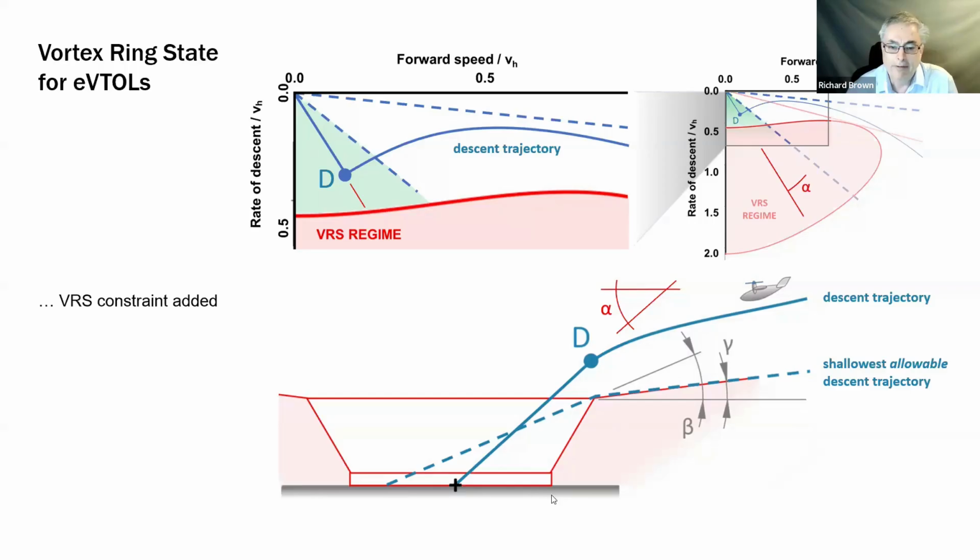It was a fairly simple argument that I made: if you defined these approach surfaces and this final funnel in terms of their geometric properties, then you could quite easily map out some trajectories that the aircraft would have to follow in entering that last funnel-shaped part of the flight envelope. You can see from this diagram that if you were to just graze the approach surface and then end up landing within there, under the most benign conditions, the shallowest allowable trajectory could be defined by this angle beta. If you were to come in any more shallowly, you would end up poking out the other side of the final funnel.